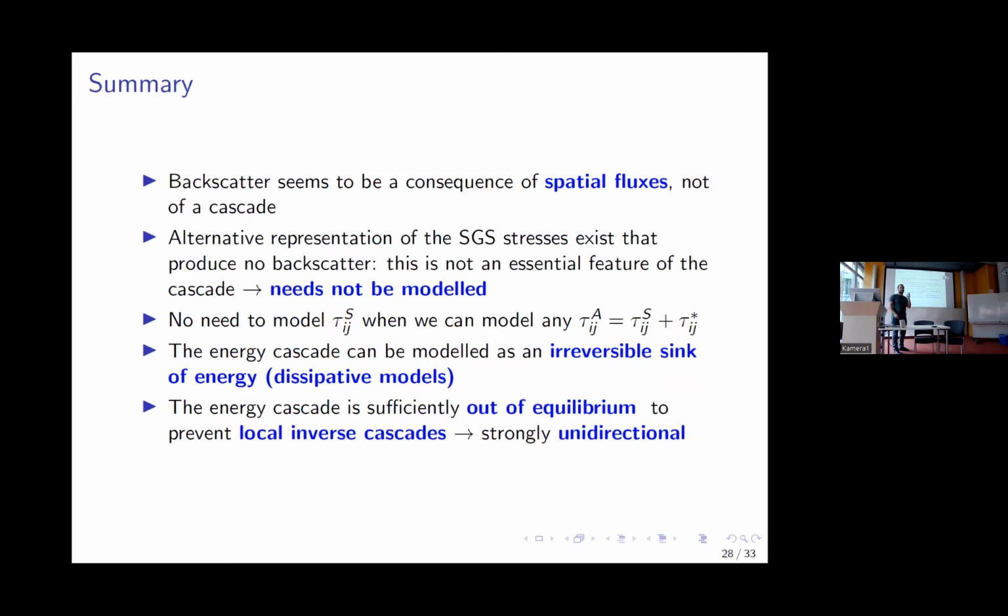Think of it, the divergence is a 3D flow, the divergence has 3 components, whereas the stress is a 3x3 matrix. It's symmetric, okay? It has 6 components. So if you try to model the Fourier scale stress tensor you have there, you're trying to model 6 components per point in the domain, whereas when you try to model the divergence, it's only 3. So you might be trying to model things that are mathematical, but not physical.